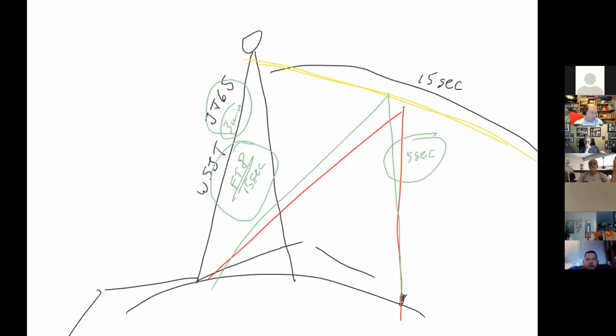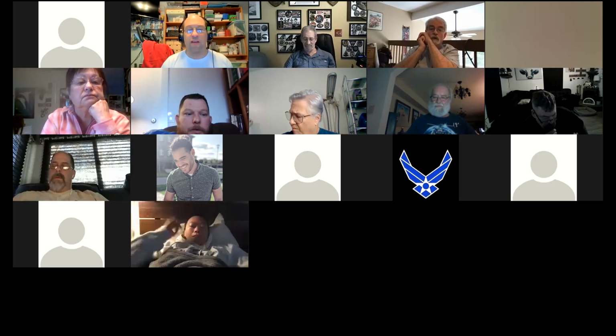Okay, we're into electrical safety. This is something that is a good idea to cover. We have to do it because it's really important. Health hazard presented by electrical current: 100 milliamps is more than enough to stop your heart from beating. Even 10 milliamps is enough to make your heart stop.